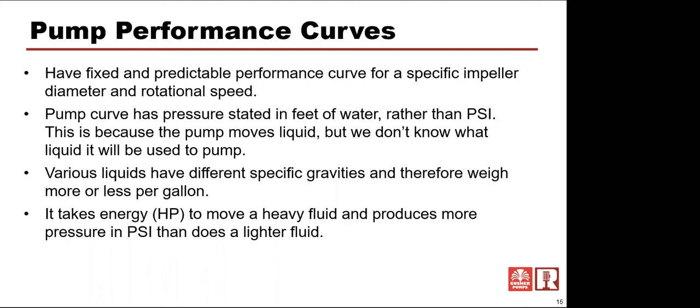When we talk about pump curves, you're going to see that all of the pump curves are in feet of water rather than in PSI. Of course, people are accustomed to talking about pressure in pounds per square inch, so it makes people confused. Your customers are probably going to say, well, I want 40 PSI. Well, with different types of fluid, the pump doesn't know the difference. It is a simple device that's slinging fluid.